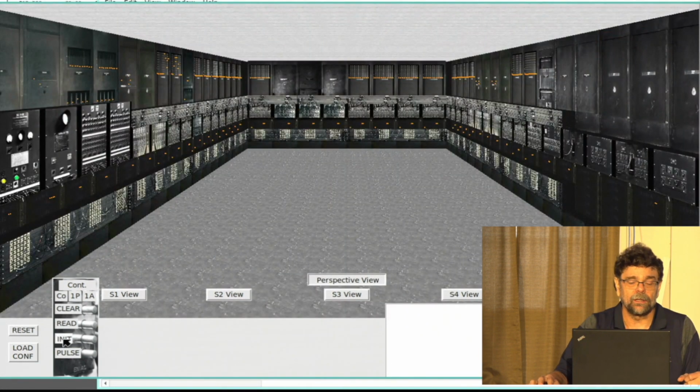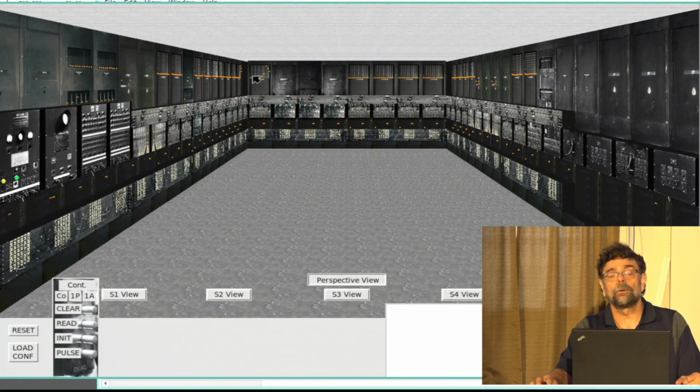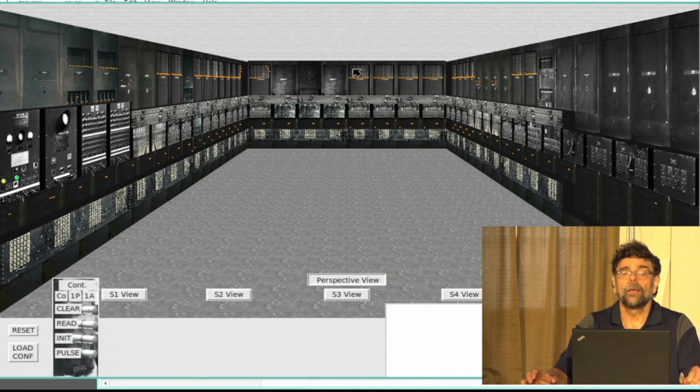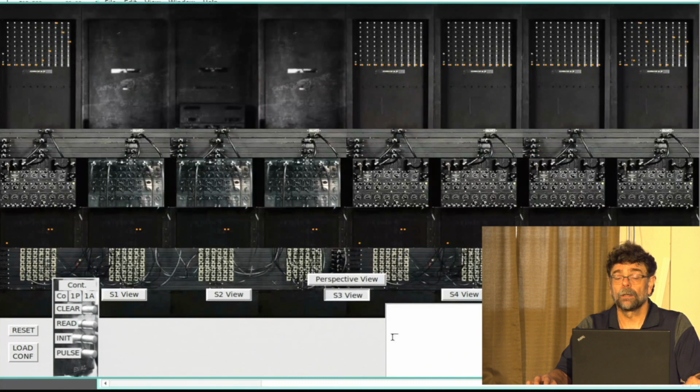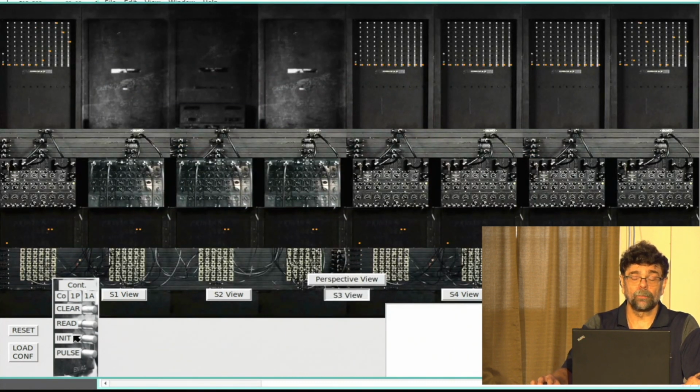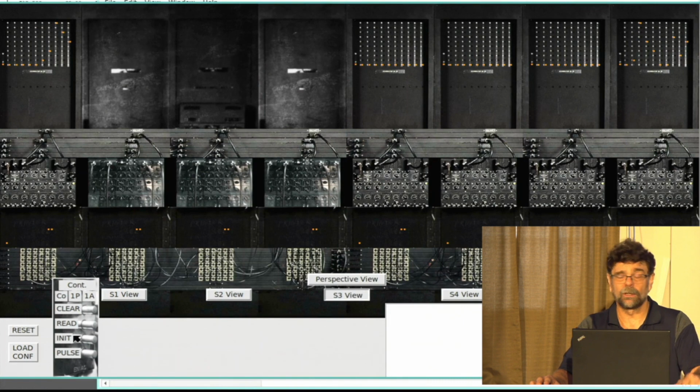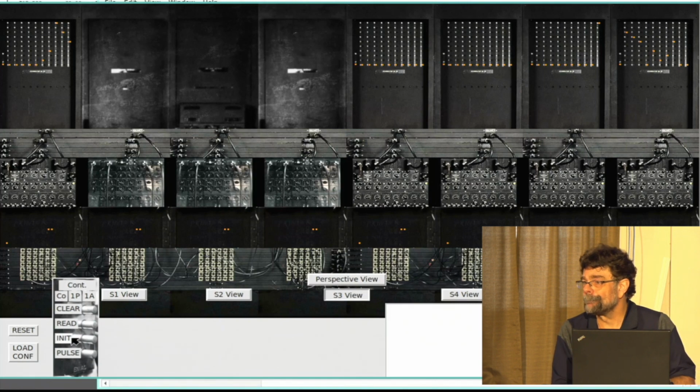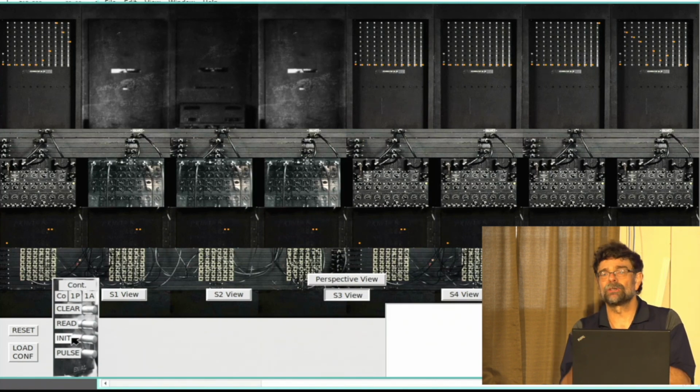So now we're going to demonstrate the multiplier. The thing we're going to do is load a number into these two accumulators back here. These are the multiplier and the multiplicand. And the product gets formed in this set of 4 accumulators over here, where the final product appears in the last 2. So if we multiply it once, well, we got an answer right here. Simple enough. Let's zoom in and multiply it another 499 times so that we get it 500 times that product. And that's it. The fact that it can do several hundred multiplications per second turned out to be what caught von Neumann's interest.